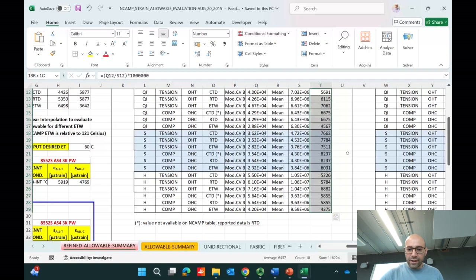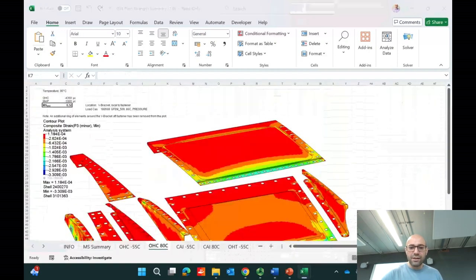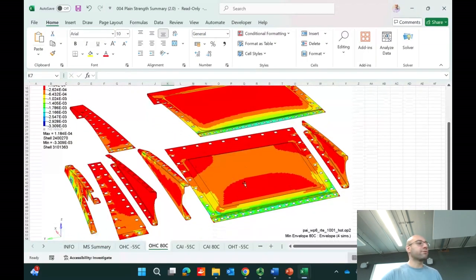And then, in this particular case, we go and simulate an FEA, we simulate a particular part of the aircraft. All of this is composite. So apply aerodynamic loading, and we'll come up with all the loading. We just mask the holes, the fasteners, because fasteners provide fake stress elevation in the contact cloth, so we mask them. So there's no fastener here, we just take away the elements associated with that. Essentially what you would get is the stress distribution in the components.